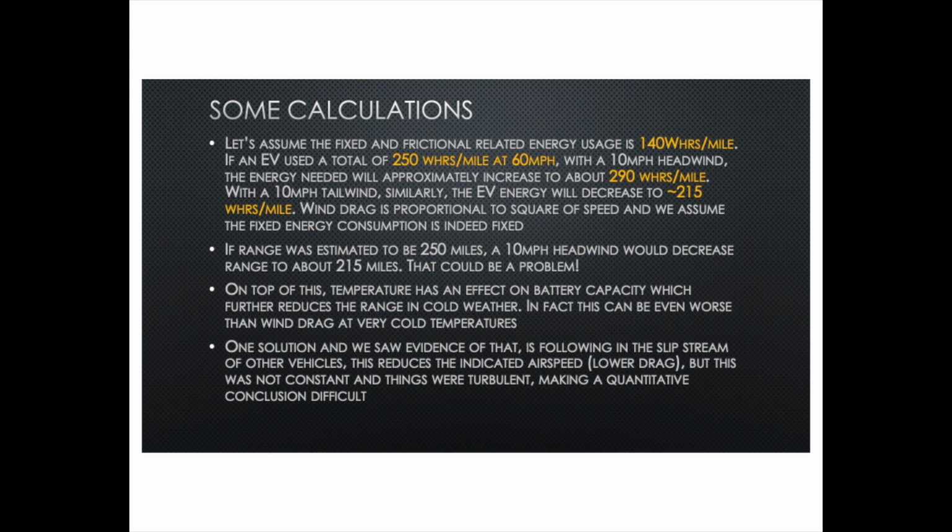So, in the case of a car which has 250 miles of range, currently charged to, let's say, typically 80-90%, most cars these days with 250 miles of range, a 10 miles per hour headwind would decrease the range to about 215 miles, and this could be a problem.